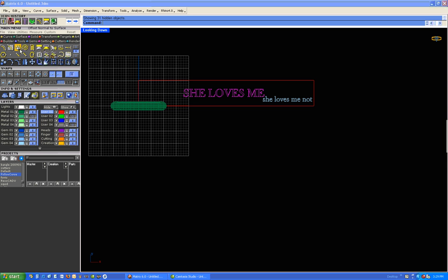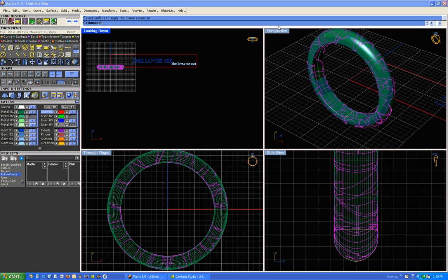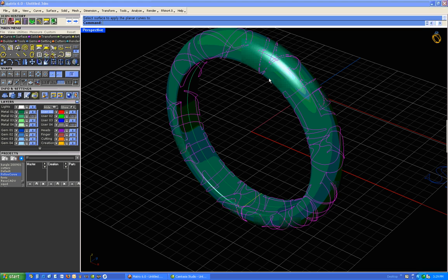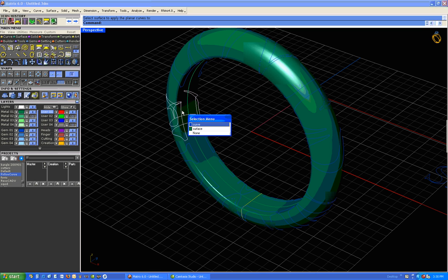But with letters, yuck. As you can see, Matrix looked at the entire text curves and the surface of the ring and stretched the text curves to evenly fit the entire surface of the ring. Not only is it distorted to the point of being unreadable, but the parts of the font curves on the inside of the ring will basically lead to the destruction of the ring. The cutter tip will come down through the model to follow these curves, hacking through everything above.